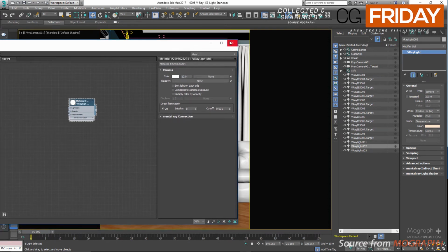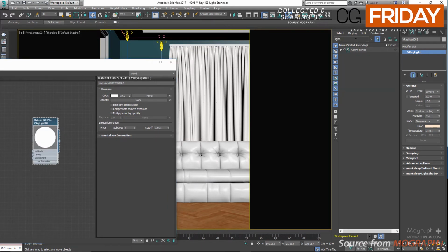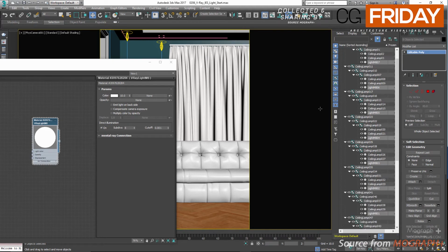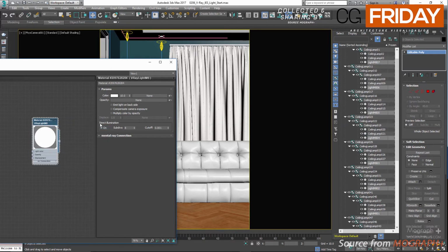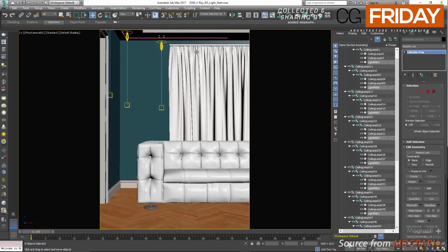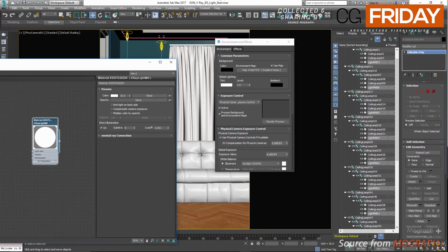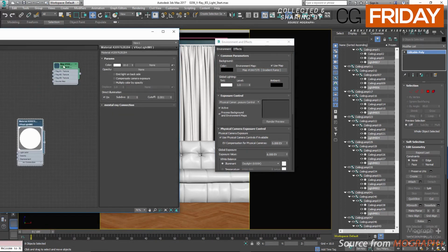Now I have renamed the parts of the light that I want to apply this V-Ray material to light MTL, just so I can select them easier. So type light MTL in the Explorer and press enter to select them. Now assign the material. Also, if I open up my environments and effects window, as you can see, I have this gradient ramp as the environment map, and if I instance it in the material editor, you can see it's a very simple map.